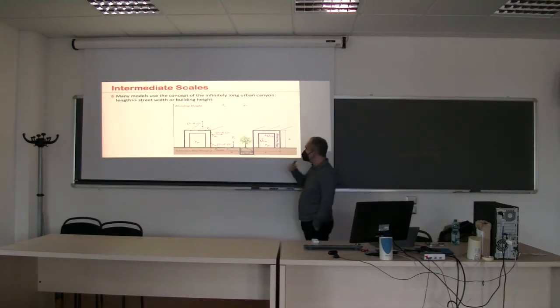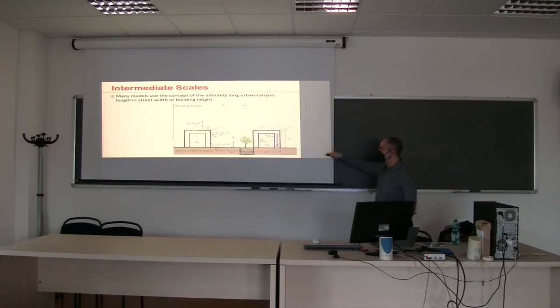From a modeling perspective, you can basically impose the temperature inside the building, and you can measure the temperature outside, and you're going to have heat fluxes through the roof that goes into the building, let's say during the summer, and through the walls. You can also divide the roof into a green fraction, a black fraction. The walls, you can divide them into glass, brick, and stone, or whatever you want. And the ground surface, you can divide it into asphalt, concrete, and some type of vegetation. So this is the street canyon.